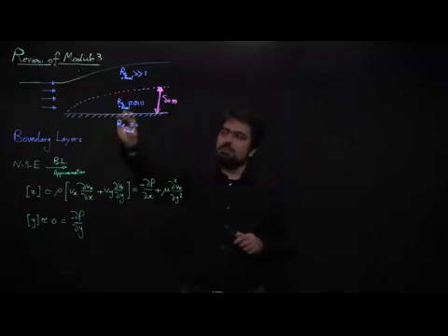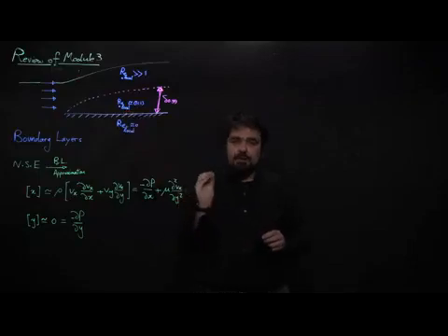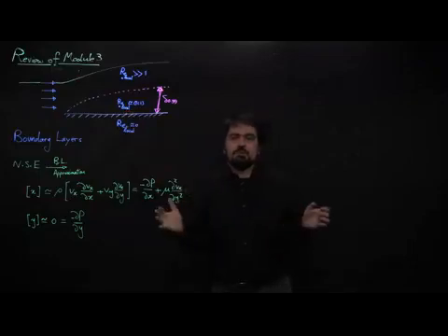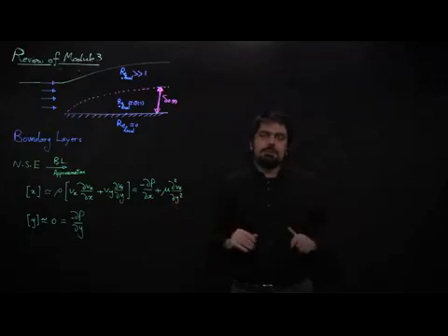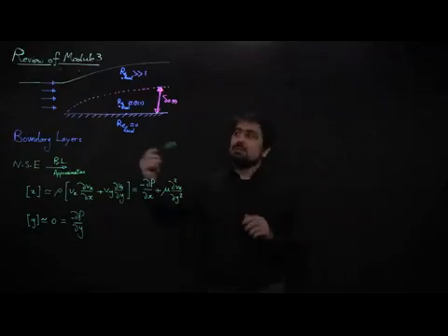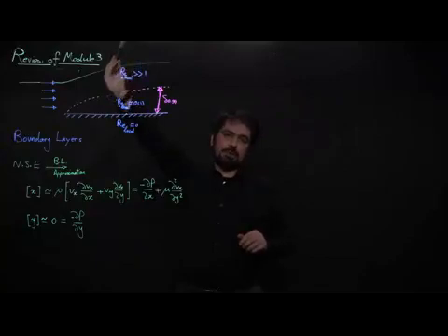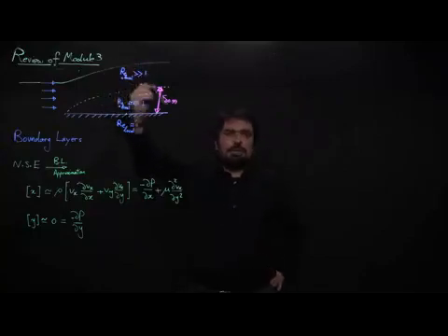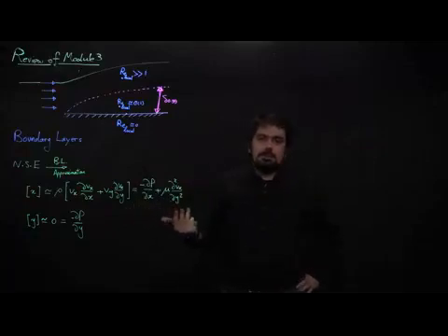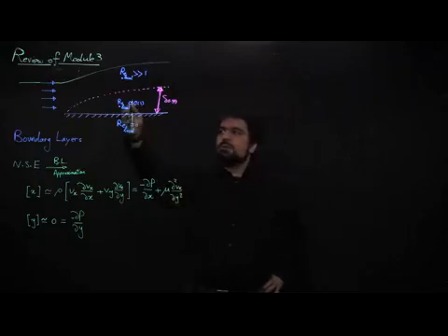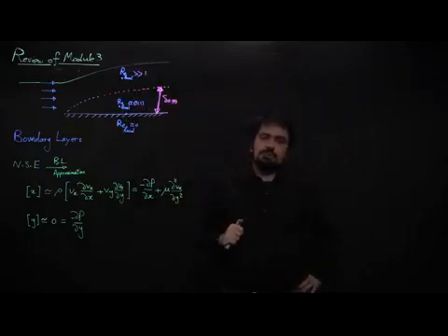So you can think that those fluid elements very close to the wall feel a flow that is very much like a Stokes flow or lubrication flow. It's completely dominated by the presence of viscous stresses. At the same time, we know that extremely far from the geometry, fluid elements will not feel the presence of the wall, or will feel very little of it. So viscous stresses, and anything related to viscous deformations, will be negligible there.